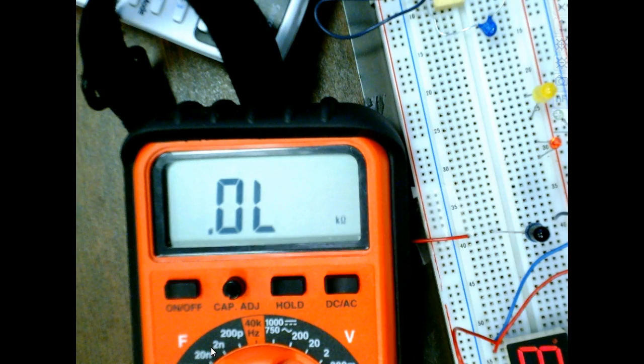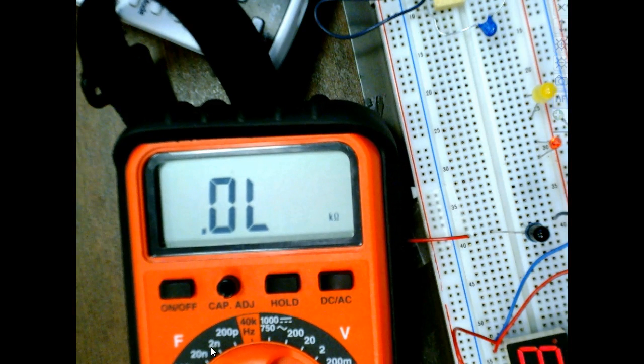So normally when you get into these 7-segment displays, they're not going to use a lot of individual resistors. They'll use what? We call these things what? Here you go, Mitchell. These are called resistor packs. This is called a DIP, by the way, which is a dual inline package. A lot of times they'll put them in what we call a SIP, which is a single inline package. And normally a SIP will have the common already set up for you.